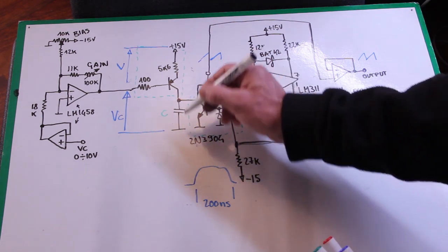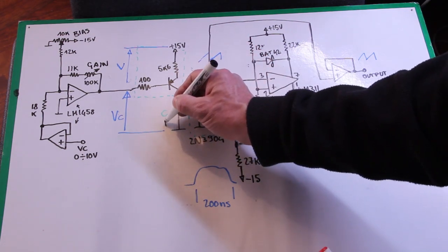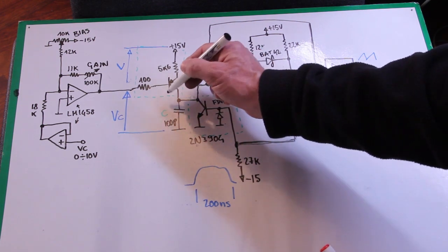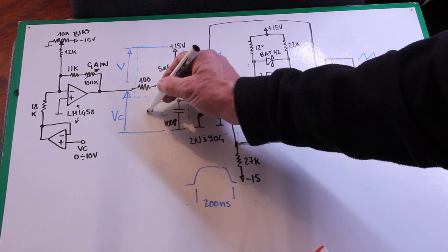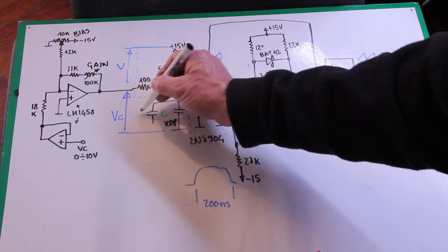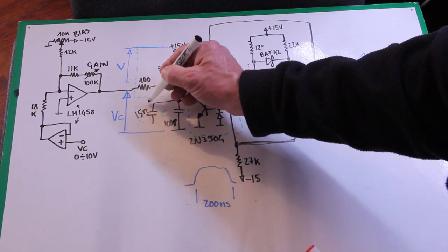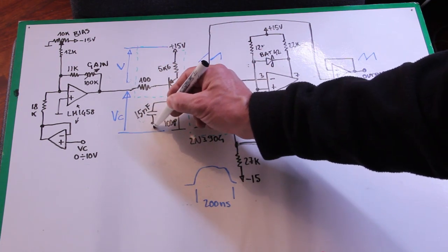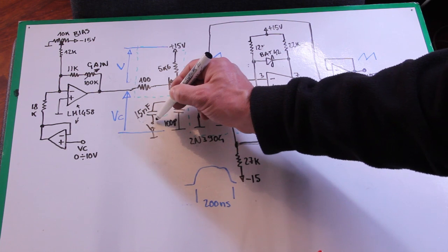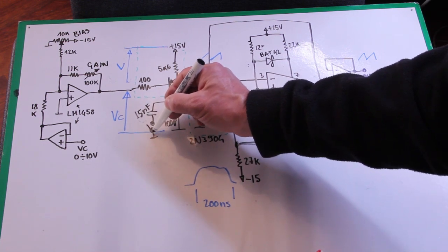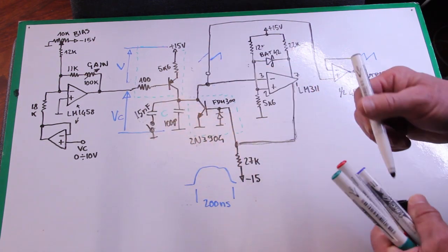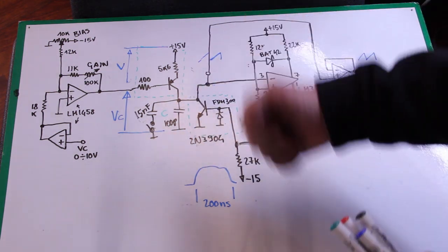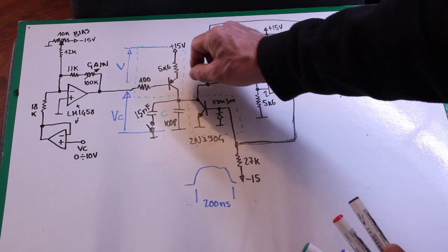So the idea is to use a capacitor of 100 picofarad here, and in parallel a capacitor of 15 nanofarad that is connected toward ground through a switch to change the range of the oscillator,